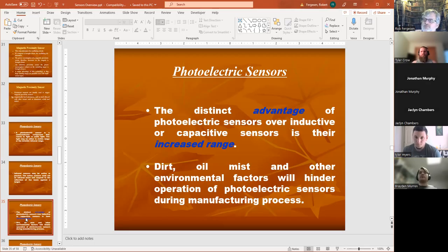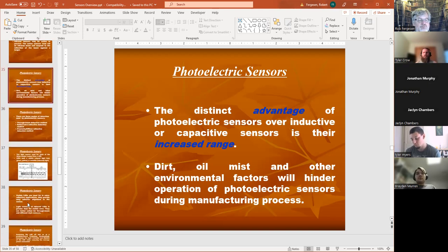In the movies, these guys spray hairspray to see where the photoelectric sensors are if they're breaking into buildings. I don't think that's real, but it's kind of cool. Yeah, if you have anything that can get into the air, if it's got enough mist to show that beam, it might also be reducing the intensity of the beam and will probably trigger that alarm. All those sorts of things make the photoelectric sensors less reliable than a prox. But distance-wise, you can't beat them.